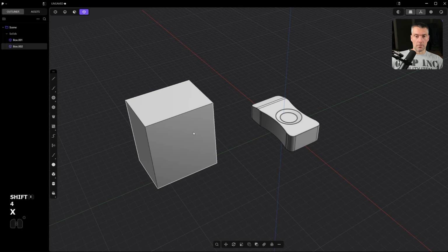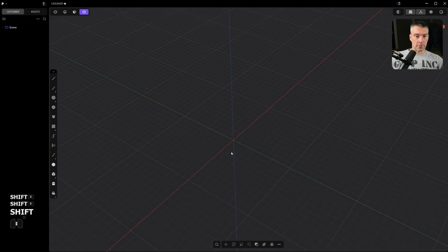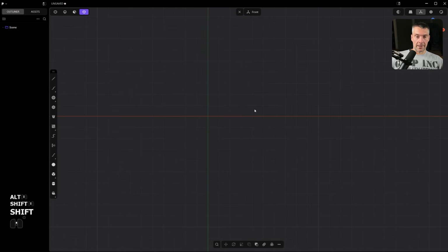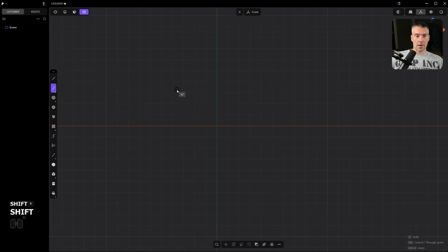Okay, cool. Now let's talk about basics of surfacing, because Plasticity is a surfacing software, so you may want to learn that. So let's say you wanted to create something more curvy, right? So we're going to grab this curve here, and we're going to go to control point curve, right? So this one. And we're going to click here, click somewhere here, go down, and click somewhere here.